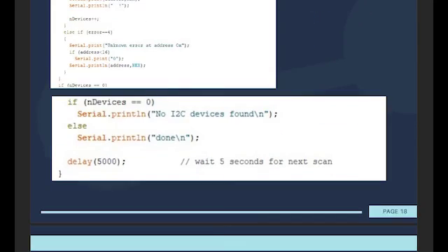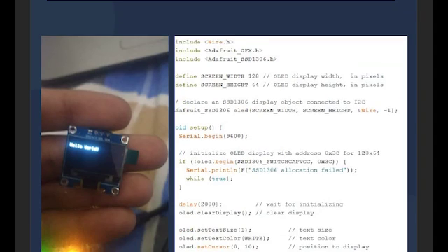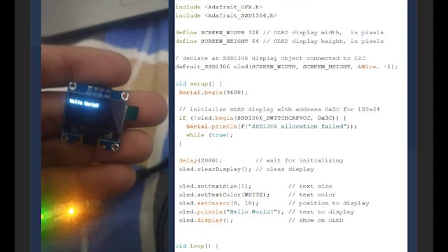The third part of the test code would be the test for the OLED screen itself, where we define all the different libraries that we are going to be using, including the Adafruit GFX and the SSD1306 modules, which are needed for printing the text on the display. What we do is we define the display with a screen width and screen height, that is 128x64 that we are using here, and a reset pin of -1, which is a standard for any I2C communication because there is no reset pin involved. And the I2C protocol itself works as a reset pin.